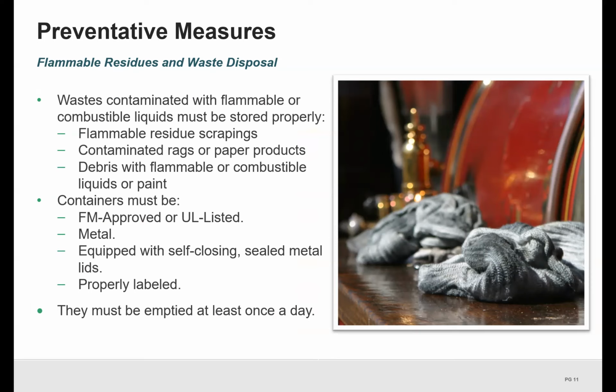Remove and place the following in containers: scrapings, used rags, waste paper, and other debris containing flammable or combustible liquids or paint residue. Containers must be FM approved or UL listed, made of metal, equipped with self-closing, sealed metal lids, and properly labeled. They must be emptied at least once per day.